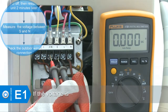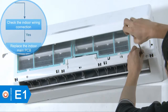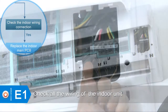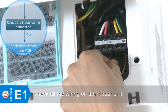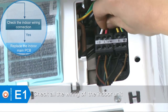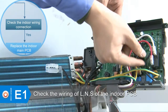If the voltage is a fixed value, possible malfunction should have occurred on the indoor unit. Main attention should be paid to the indoor unit. Check the wiring of the indoor unit, which includes the power wires and the connecting wires between indoor and outdoor units. Check the wiring of L, N, S of the indoor PCB.